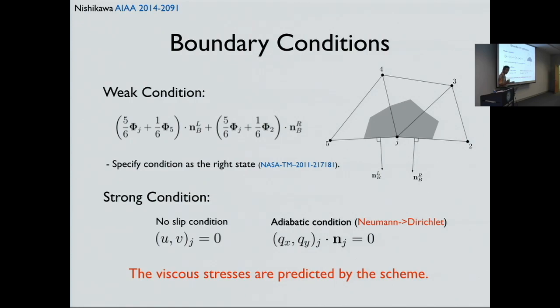But the derivative is a variable. So I just use this variable and specify. Yeah. And also remember, these discrete equations are consistent with original Navier-Stokes. It's time derivative added, so you may need additional initial conditions, but not additional boundary conditions.